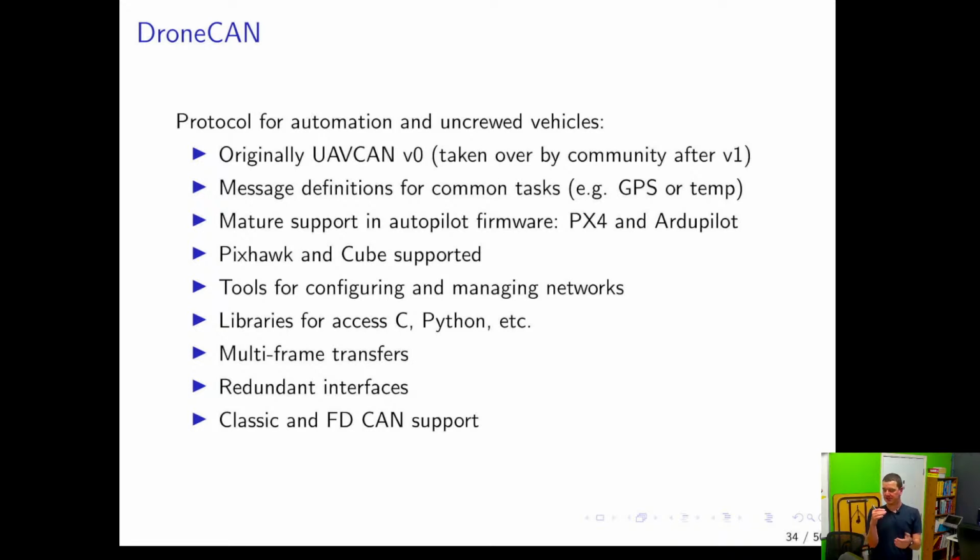And because it's so hyper complicated, sometimes it doesn't want to fly, and you're like, why is it not flying? And you have to find that it's unhappy about some sensor calibration. When I was in Minnesota, as a side part of that statement, I would pack all my gear in like minus 20 to go to the field to fly my drone. I get onto the field, and PX4 is refusing to fly because some wire is slightly loose, or voltage drop because of the temperature, and you have to pack your stuff and go home. So anyway, I would say use ArduPilot if you're building drones. PX4 is maybe more of a research project, no disrespect.